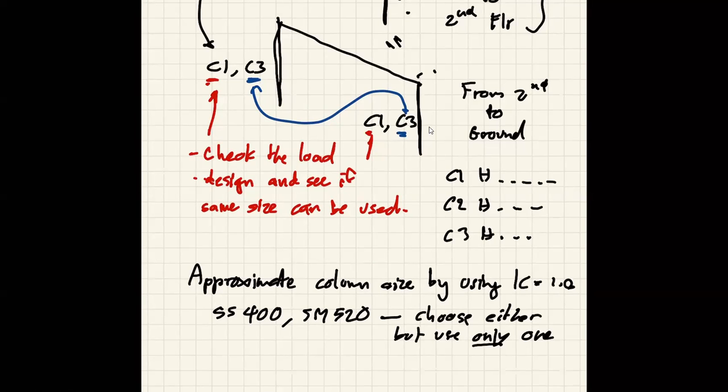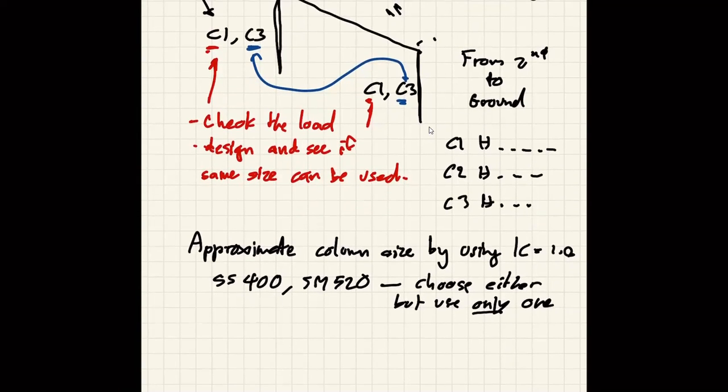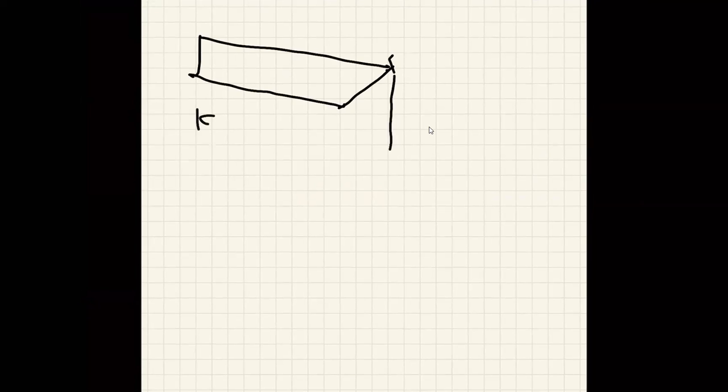And this is for your column. And for your truss, once you know the load, you're free to choose whatever your configuration is. Okay, I think we have like 6 meters, right? You are going to have 5 panels, because I'd say we have 5 purlin at every 1.2 meters, right?